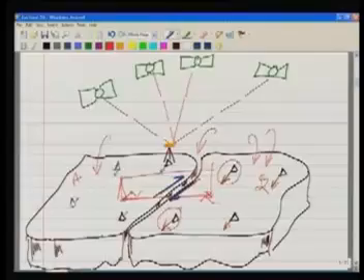In this case, this landmass as well as this landmass both may move. If the movement is the same in the same direction, the vector between the two points will not change. But in the case of GPS, each GPS point is being independently measured with respect to the satellites, and satellites are not going to be affected by slight movements of the land masses. So this is a very important technique and is being used.